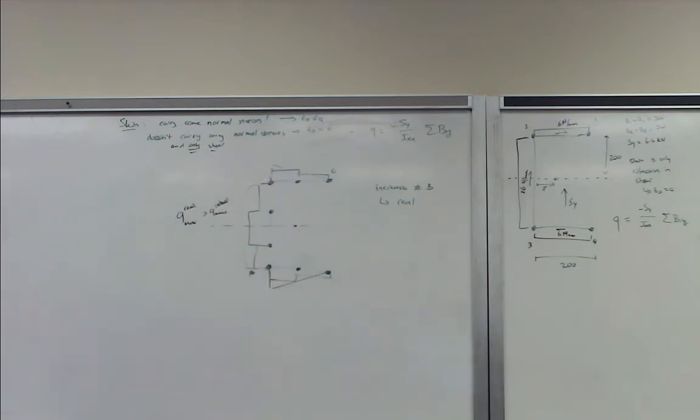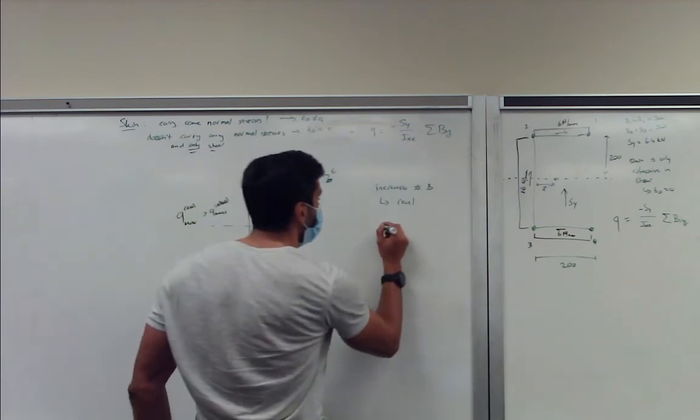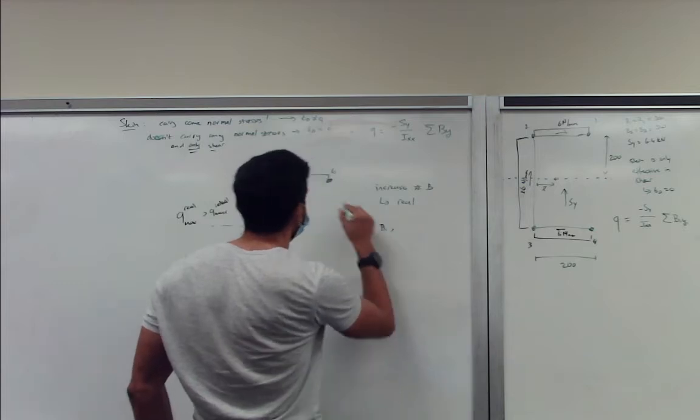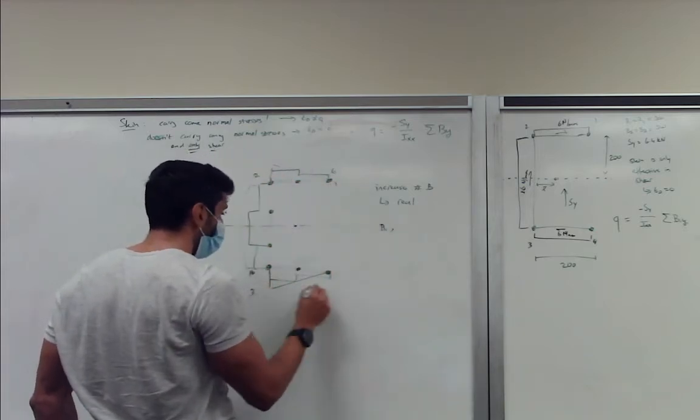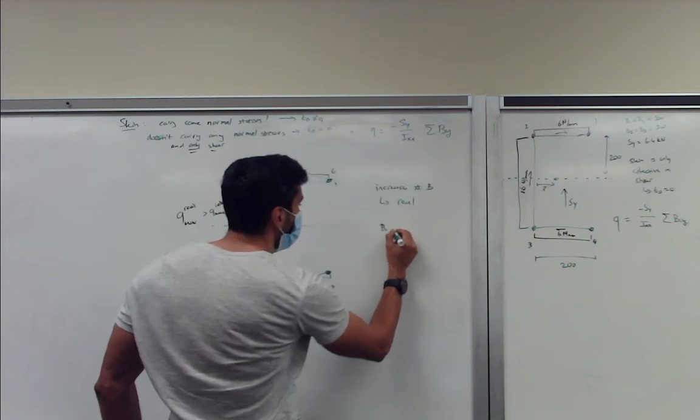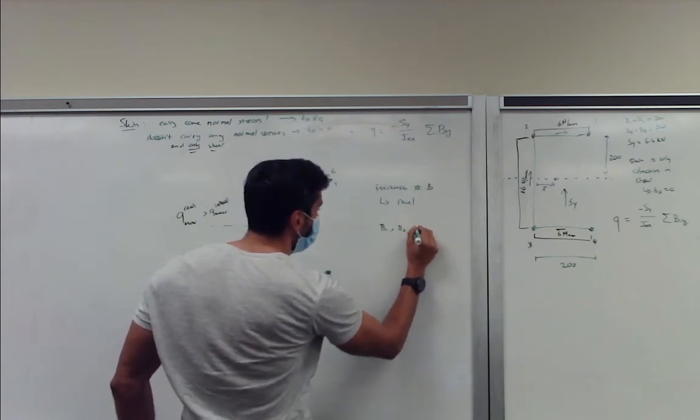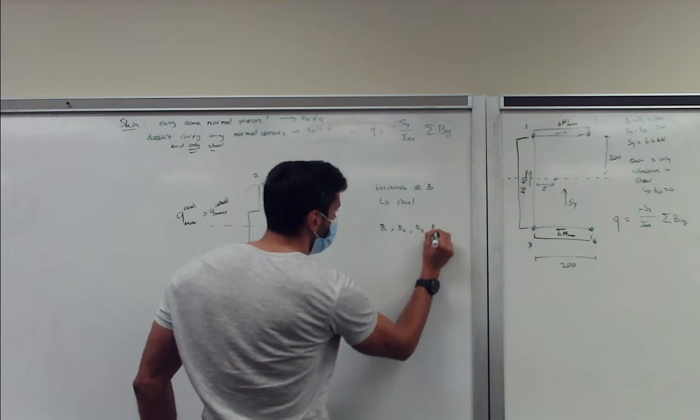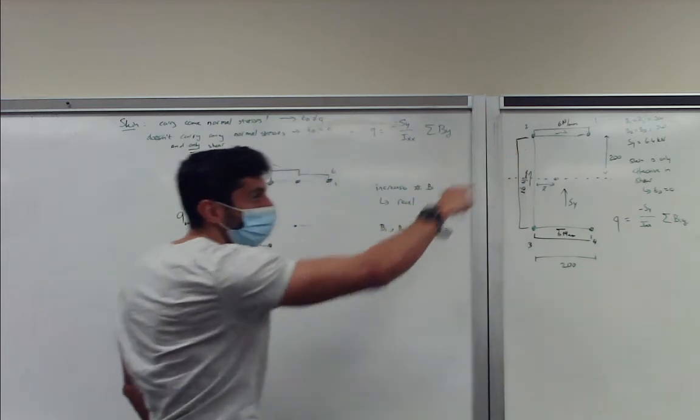As well, we can somewhat, in a simple manner, say it's equivalent to a finite element code, where we increase the number of elements, and we can approach the real solution. But the booms added should have the same area as the others. You have to calculate again what the equivalent boom areas are. So if you add more booms, your B1, B2, B3, and B4 will no longer equal those.